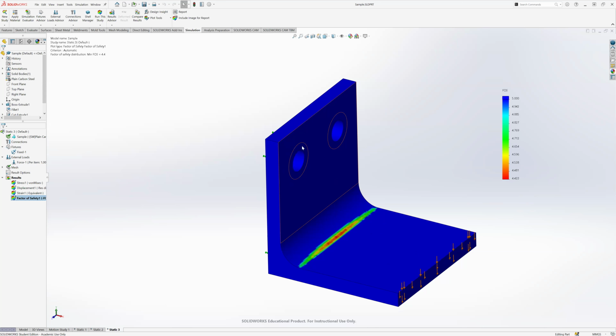Let's say the stock you can get is exactly this shape. You can remove more material to reduce weight, but in that application it's really not helping you. It's actually costing you more money because the material is going to be the same, but you're having to remove more material by machining. It takes longer. So in some applications, you'll have stuff like that where it may not matter too much.